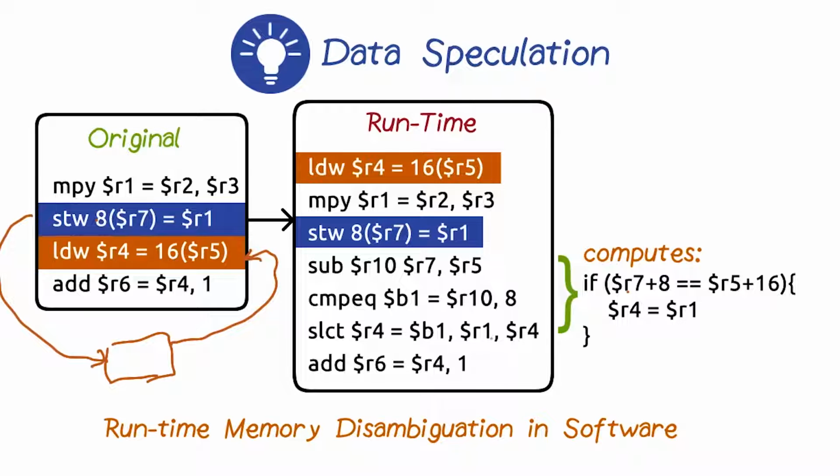And then we have finally a comparison operation here. If the B1 bit is set, then we are going to copy the value of register R1 into R4. Why is that? Because under that situation, the right value would be sitting in R1 here, as you can see, which was used for carrying out the store. And a wrong value, or an old value, will be sitting in R4.